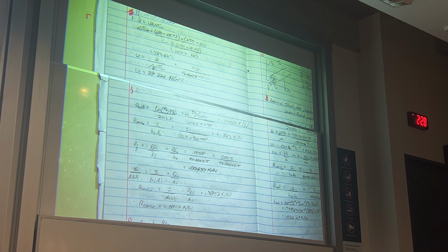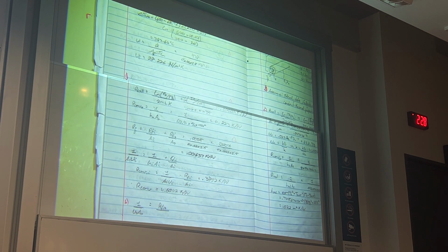That makes sense. Obviously our convection through our water and air is limiting compared to the conduction through the steel tube. Intuitively it's much easier to heat up a steel pipe than water or air, so we would expect convection to be the limiting factor with the highest resistance. And then that's when I gave up, or I couldn't figure out part H.